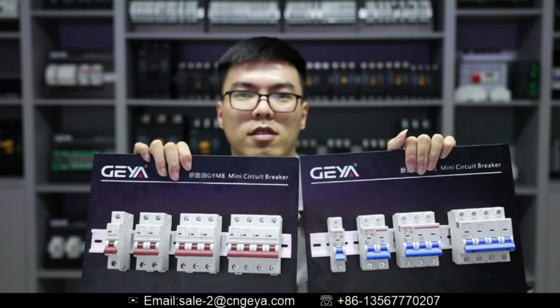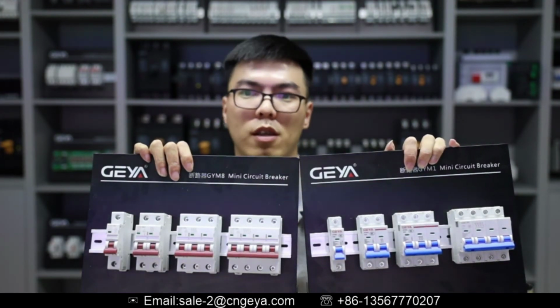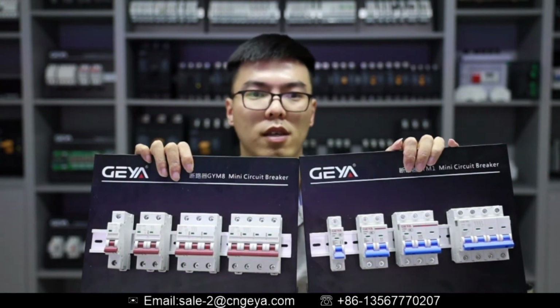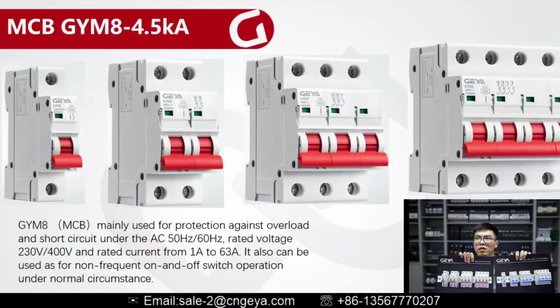You can find they are very similar. They are both 4.5 kiloamperes breaking capacity, and they both can go from single pole to 4 poles. They are both from 1 ampere to 63 amperes. The only difference is this one, their appearance is different. You can check the terminal and the handle. They are in different structure.